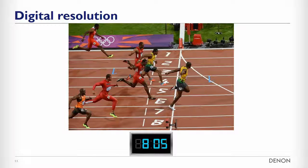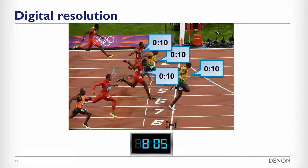So what sampling rate do we need? It all depends on what we want to achieve. Let's go back to the digital clock example. Imagine that such a digital clock would be used to measure times during a professional 100-meter sprint competition. Let's assume that the indicated time shows minutes and seconds. Using such a clock during this contest would be useless, as all participants would most likely finish with the same time of around 10 seconds. The resolution of this digital clock would be too limited for this application.